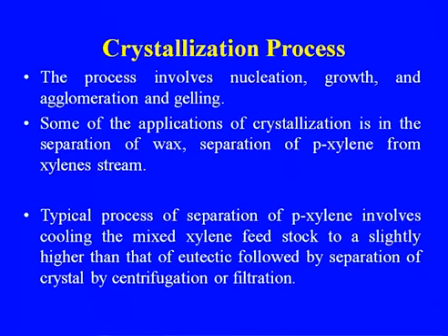Crystallization process. Earlier it was limited to the sugar industry, where crystallization of sugar separates the molasses from the sugar. But now it has come in a big way in the separation of close boiling point components, especially in the separation of paraxylene from the xylene stream. The process involves nucleation, growth, agglomeration and gelling.